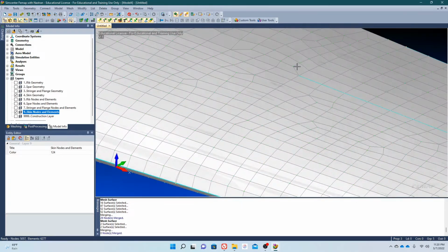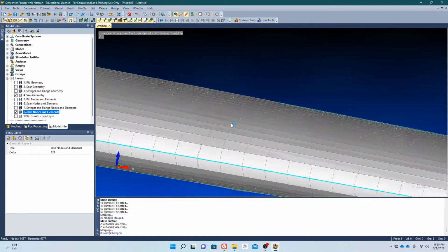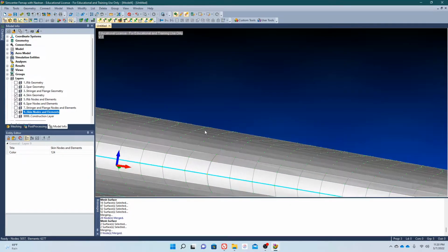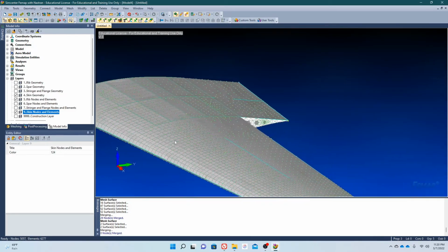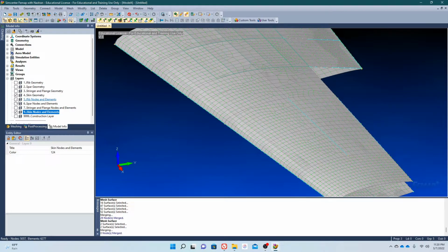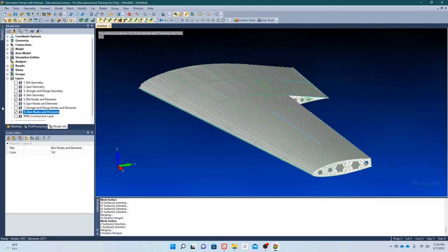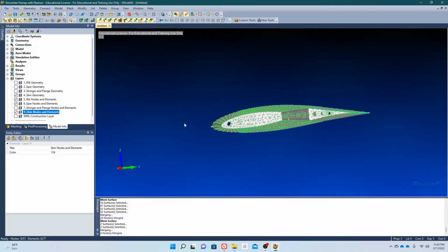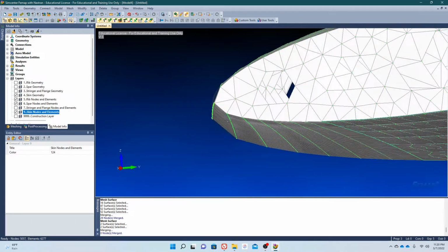Right. So that's a nice mesh right there. Now again, if we notice, there are certain elements that seem to not have nodes, and what's happening there actually is they're present in the rib layer. So the connectivity, because of these nodes, is super important, and it's very, very crucial that they're there, and they show up just like they do right there. And when we turn it off, clearly see the connection right there, so that's good. That's everything we need.